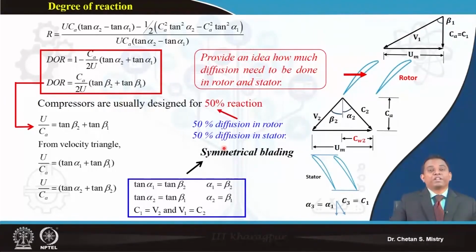And the purpose of the stator was to guide the flow. But looking at this, you realize the stator is also doing diffusion work. So it is not only to guide the flow. There are many designs where people do diffusion both in the rotor as well as in the stator.